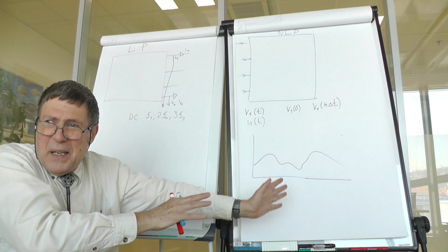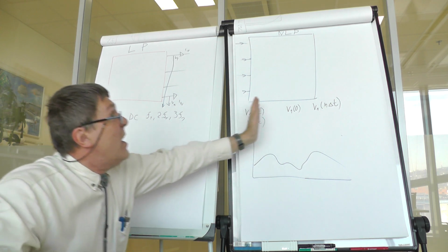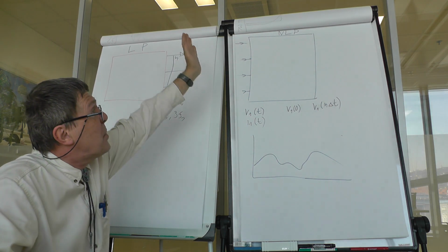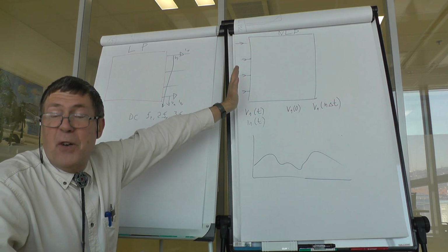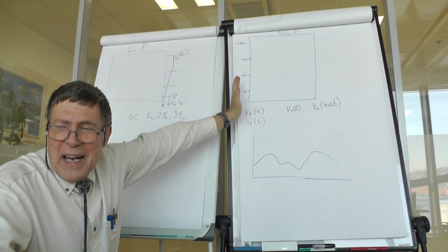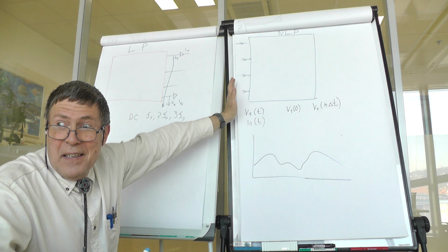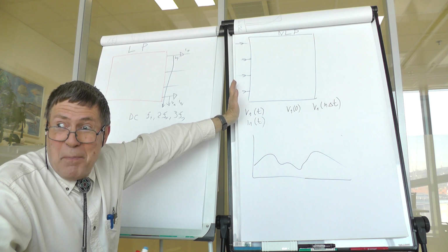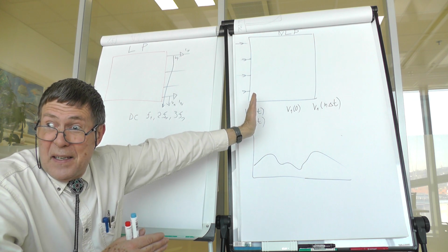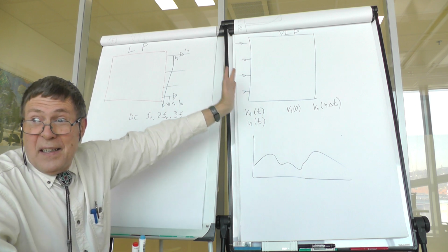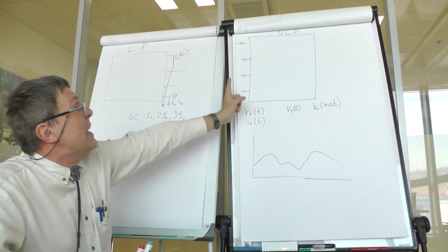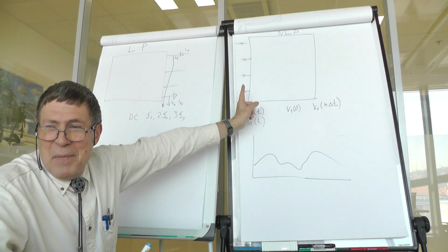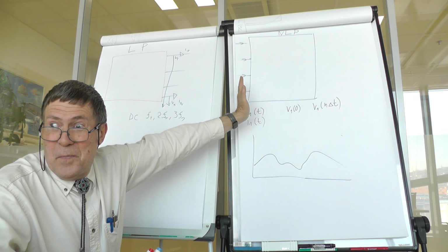So possibly he has suggested proper voltages so that after the whole process we have got the same time domain sets of samples. And this is called harmonic balance, because you run the whole simulation and you get the same at the output you had at the input.